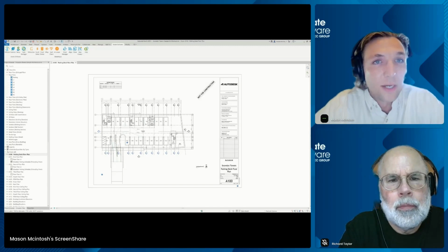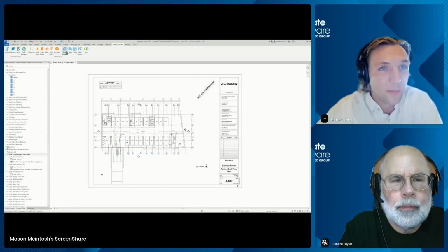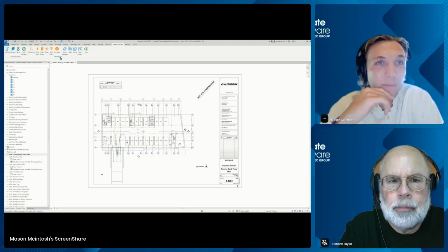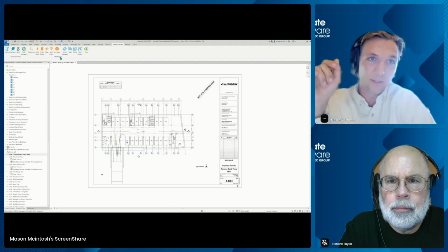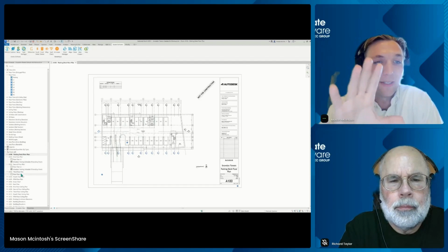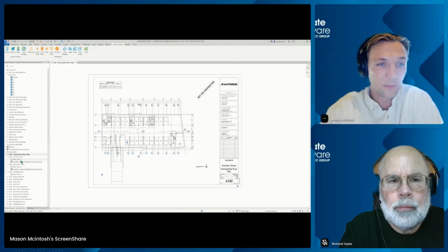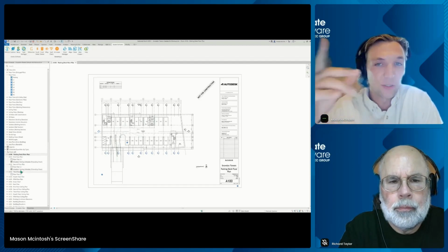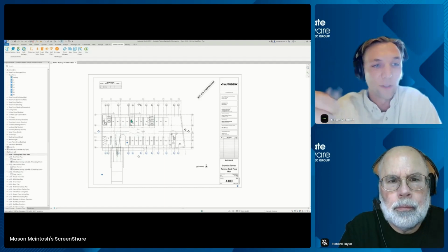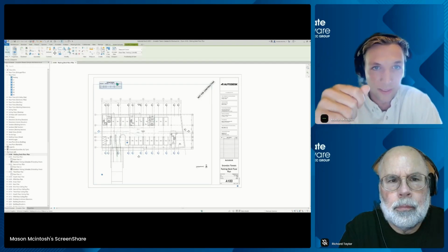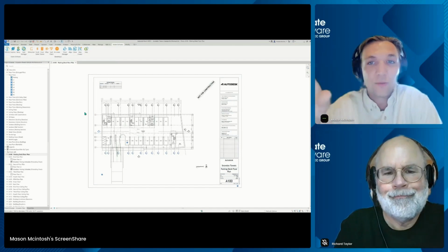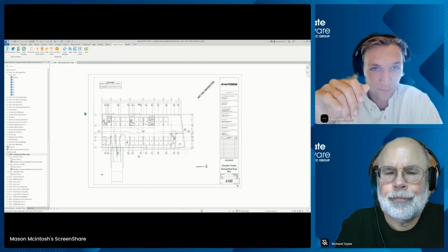So within this, we're now in Revit. On our Revit page, our Ideate software is at the top, and we have our sheet which we're going to be using as a reference. Our Ideate apps are up top, and we can see all of the different options that we went through at the beginning. Now we are essentially trying to take all of our different floor plan views and align them perfectly by using one of them as a reference. You can see that we have a parking deck floor plan, first floor plan, second floor plan, third floor plan. We have our parking schedule.